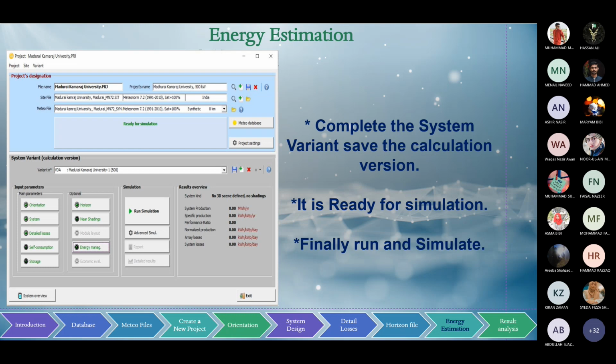Once the system size is defined, suppose we are going for a rooftop system, the option to enable multiple string inverter subsystems is also available in PVsyst. The module manufacturers' modules are given by default in the PVsyst software. So we can select what type of module we are going to use in this project, and what the voltage is, everything we need to consider.